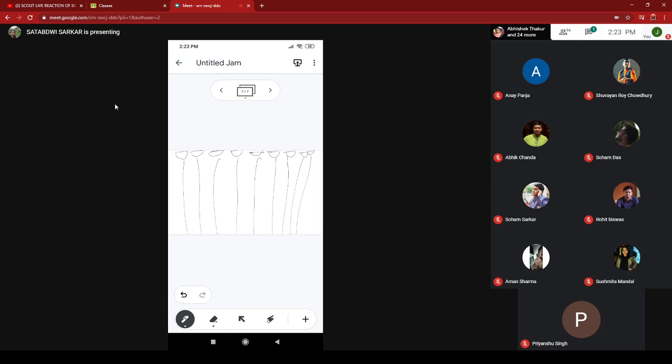So these are the outputs of the AND gates, and we have to connect this with the OR logic, with the number of OR gates that we have in our function. So we have X, Y, Z as our function. So I told you before that the number of OR gates will depend on the number of functions. How many functions we have? We have a function as X, we have a function as Y, and we have a function as Z.